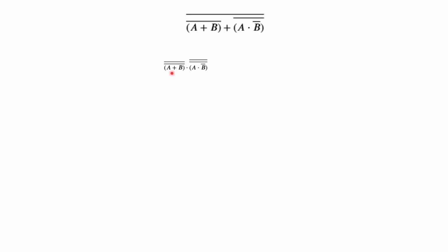Well, what else can we do with this now? Can we simplify that? Well, yeah. You see, we have a not here, and a not here, but not yet. We could just simplify that, because a negative of a negative, they cancel. So we can just eliminate that, because one negation eliminates the other one. So it turns into this, and that negation bar, the not bar, stays.